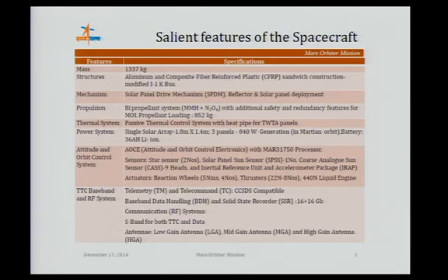Attitude and orbit control system is basically a MA31750 processor, sensors, basically star sensors and solar panel sun sensor, coarse analog sun sensors are adopted in this, and inertial reference unit and accelerometer for LAM cutoff and other related operations. Main actuators are reaction wheels, 4 reaction wheels in tetrahedral configuration, and thrusters, and 440 Newton LAM engine, which is used for orbit maneuver and Mars insertion.